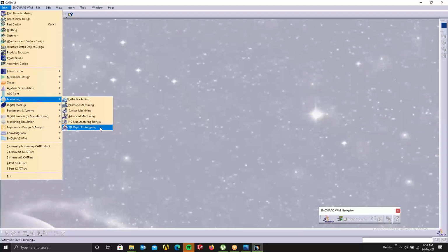According to the tool they will generate a tool path, and that tool path will have an NC program. This NC program can directly be transferred to the CNC machine. You put a block, as an aluminum block or any job block, and as per the NC program, it'll remove the material. Understood?